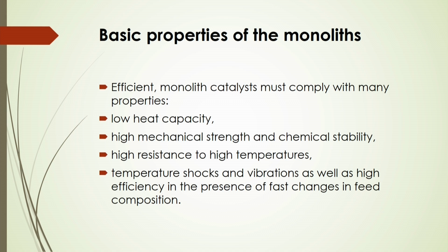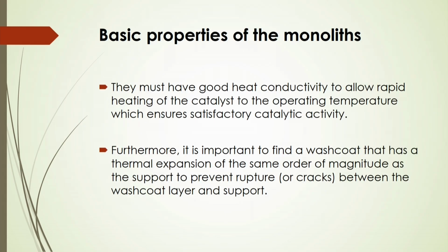So, these are the basic properties of monoliths that should be known before going to the design of the monolithic structure. Monoliths must also have good heat conductivity to allow rapid heating of the catalyst to the operating temperature, which ensures satisfactory catalytic activity.